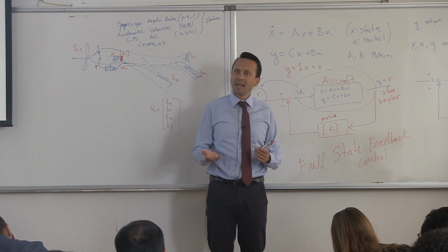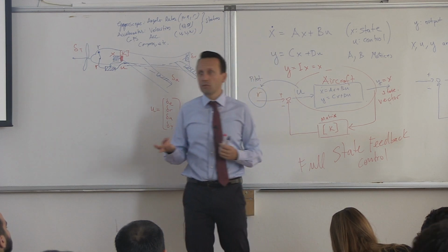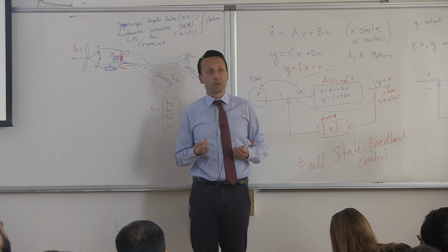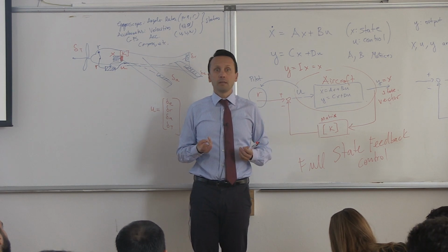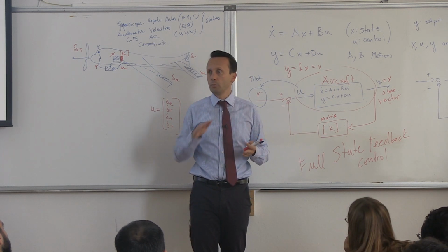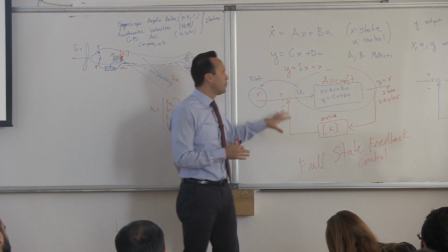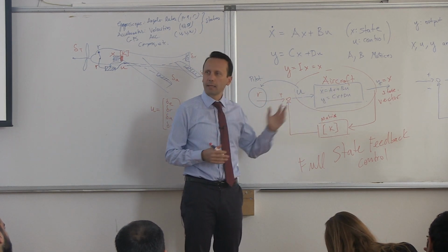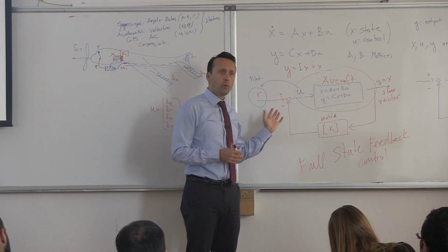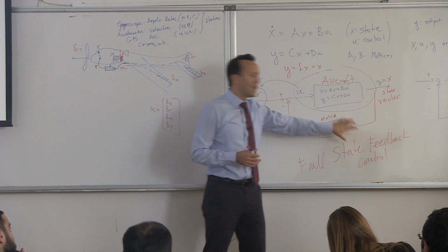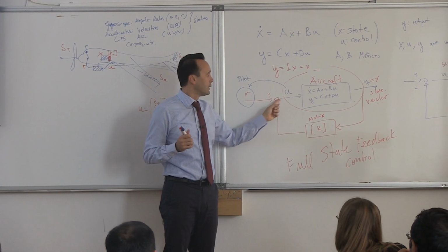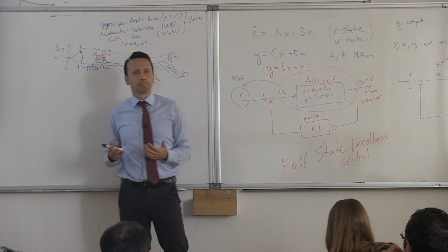You would stabilize it. You can stabilize the airplane with this if it's not stable enough. You can actually destabilize it too if you would like to. You can design this in different forms where you can navigate now with your airplane. You can design a whole autopilot with this idea. Of course, the architecture looks a lot more complex. We will talk about this in this semester. But the idea is always the same. You measure things, send back, multiply with something, go back and alter the control of the airplane so that the airplane behaves differently.